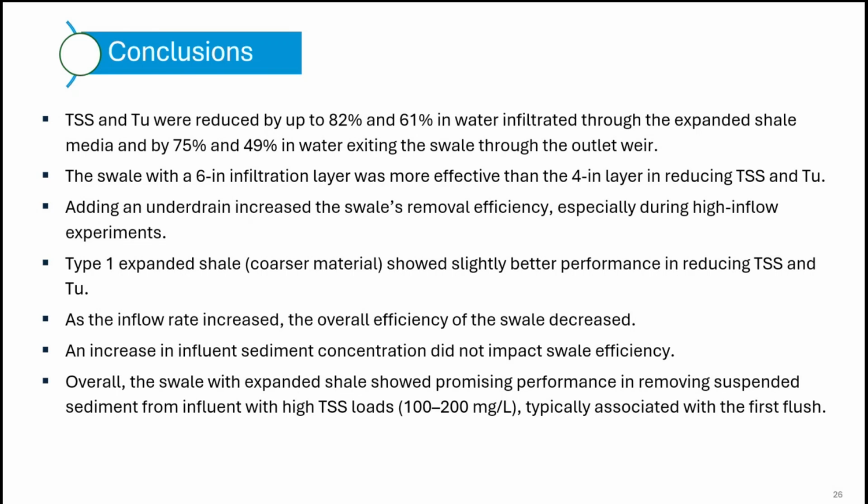Type 1, with the coarser sediment or coarser shale, performed better than the finer one. And then as the inflow rate increased, the overall efficiency of the soil decreased, as we saw. An increase in the influent sediment concentration didn't change the performance of the system. And overall, the expanded shale showed promising performance in removing suspended solids compared to other types of material, especially sand. Next one, please.